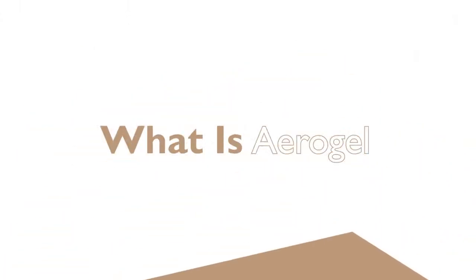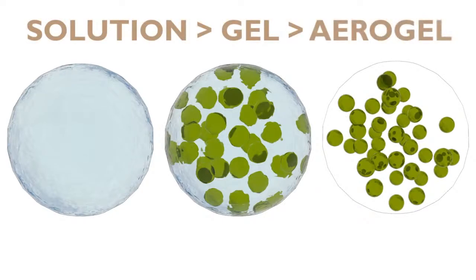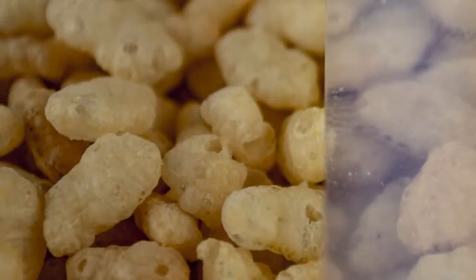What is aerogel? Aerogel is a very low-density solid that was developed in the 1930s, but has only recently found mainstream uses. An aerogel is a gel in which the liquid is replaced by gas without shrinking via a complex process called supercritical drying. The silica aerogel used in Spacetherm insulation products is essentially puffed up sand, best described as being to sand what a Rice Krispie is to rice.